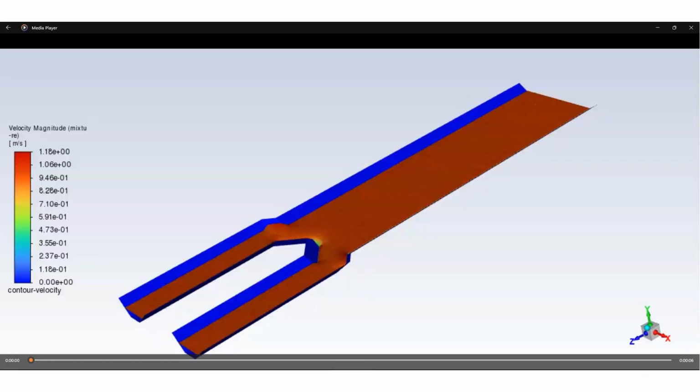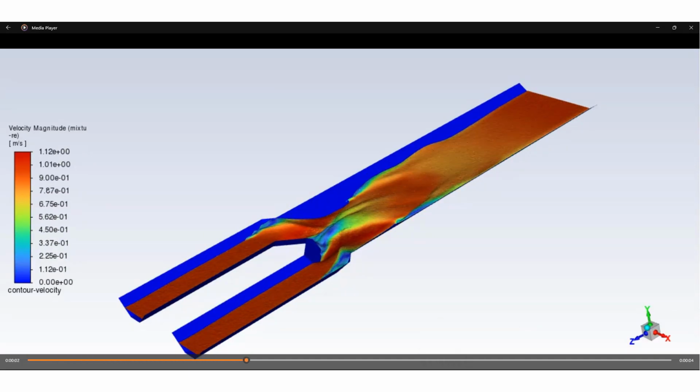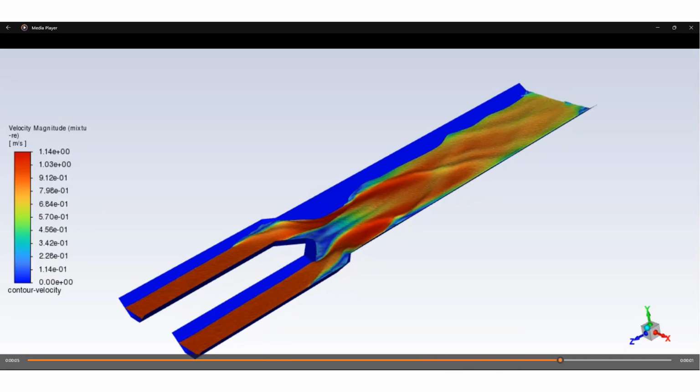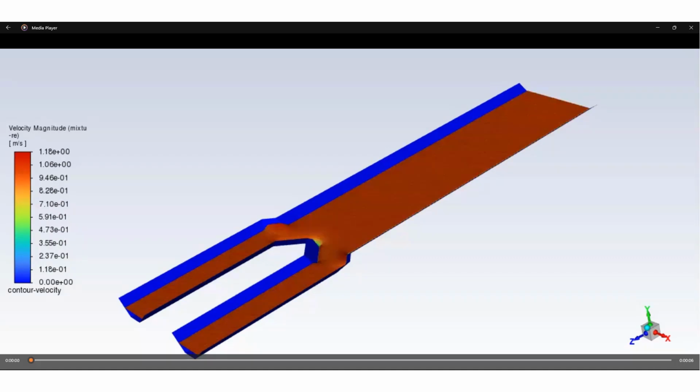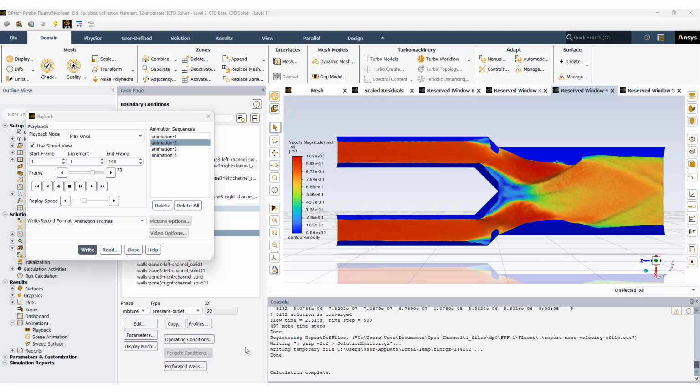So we can see that the water depth is a very important parameter in the flow regimes in open channel flow. In the theory of open channel flow, the flow regime depends on the Froude number, which is in terms of the velocity and also the depth of the water in the open channel, and we can have different regimes, subcritical or supercritical, inside the open channel.